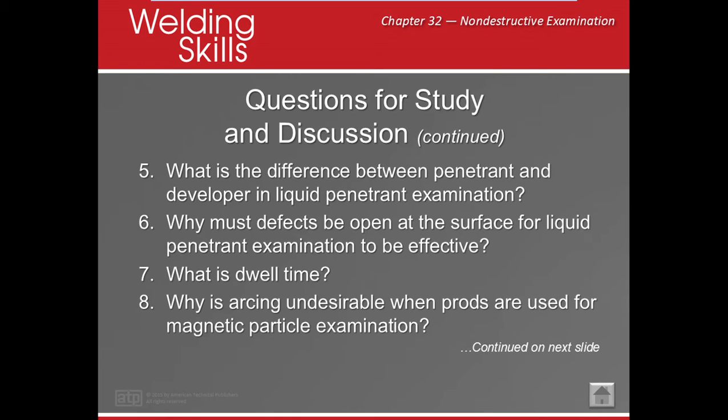All right, what is dwell time? Dwell time is the total time the penetrant is in contact with the component surface, including application and drain times. This is important because this is on a lot of tests, let me tell you.